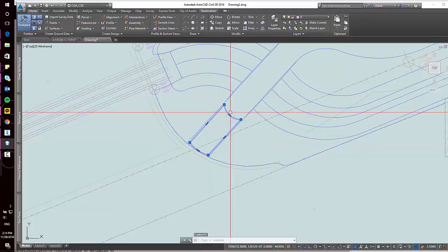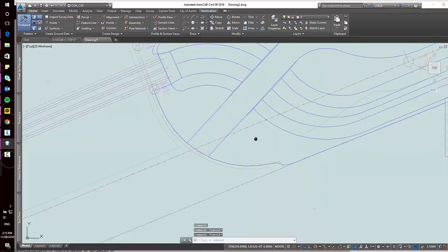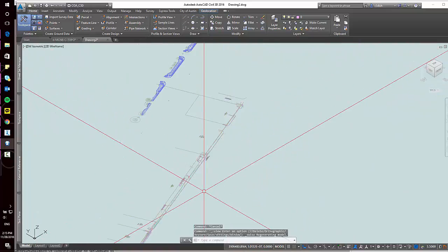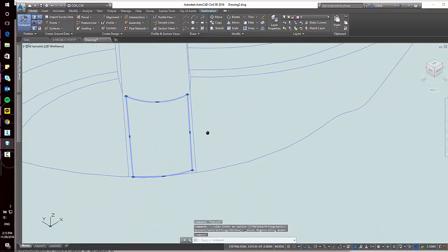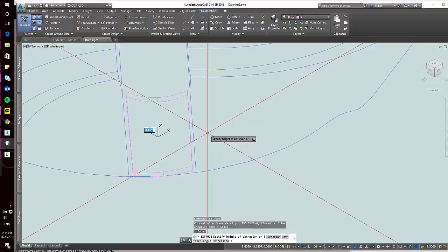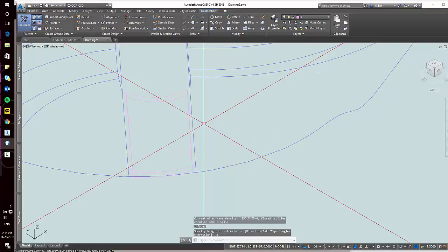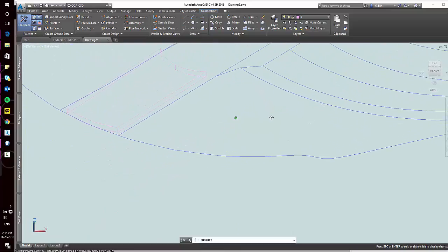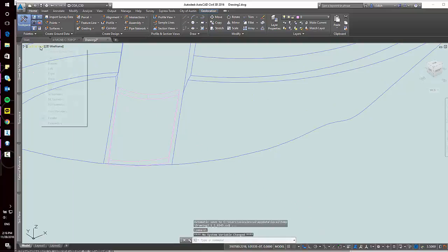We can go forward and do the rest of the stuff. So right in here, you're gonna see there's a polyline. At properties here, we're gonna assign an elevation to make sure that it's above the elevation model. We're gonna change the view to a southwest isometric view so we can see what we do in a 3D environment. Right in here, we're gonna have the element. We're gonna do an extrusion to convert it to a 3D object. We're gonna extrude to 0.5. We're gonna do a 3D orbit now, and we're gonna see that it's an extruded object, and this is the object that we should be able to export.